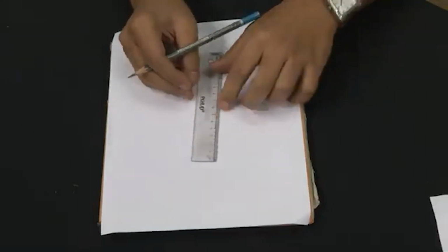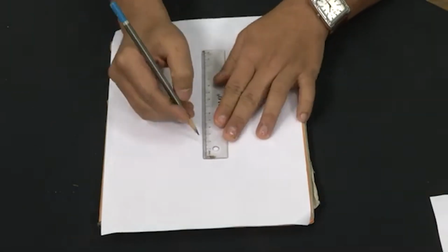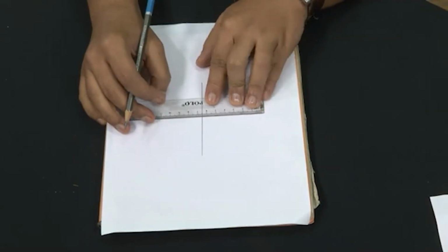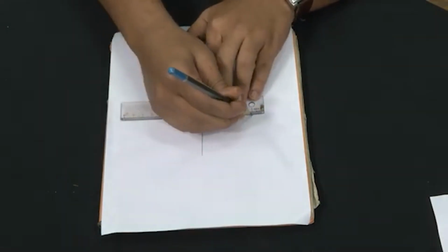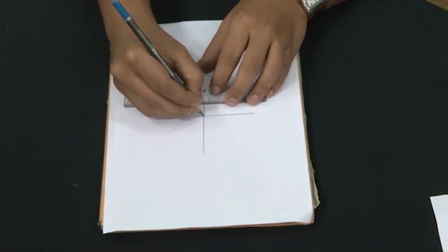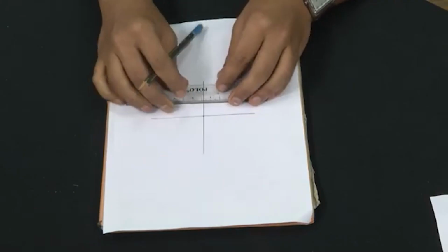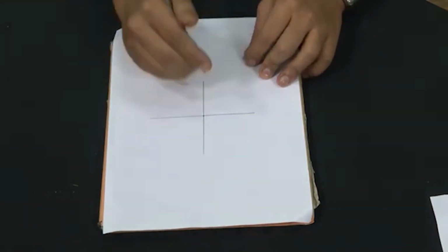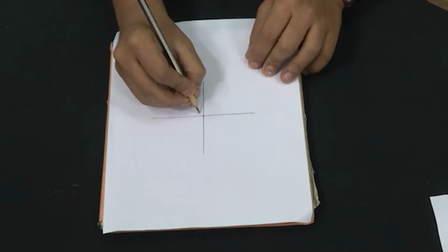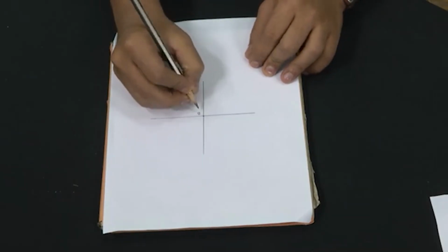So, again for this problem, without the help of a stereonet, we will try to find out the orientation of the ore body. So, again on a blank A4 paper, first we draw a biaxial diagram to fix the coordinate system. Now, we plot the spatial disposition of the boreholes. So, first we fix a borehole at the origin. In this problem we fix the borehole B. Suppose this is the borehole B.